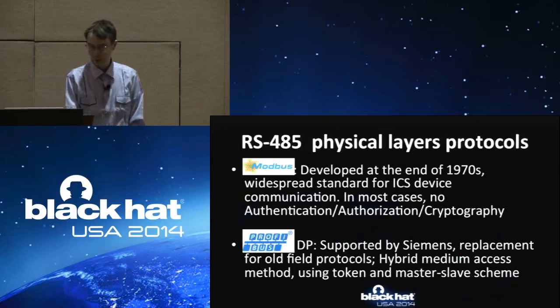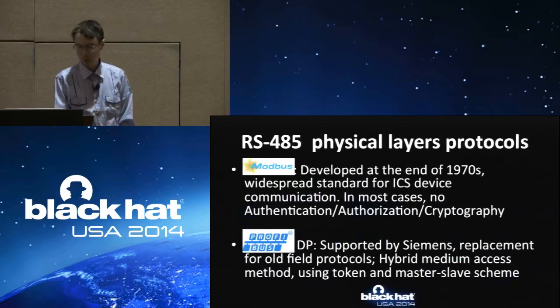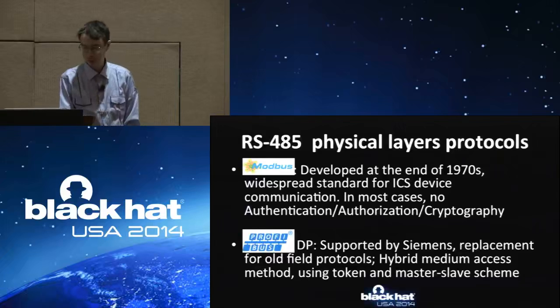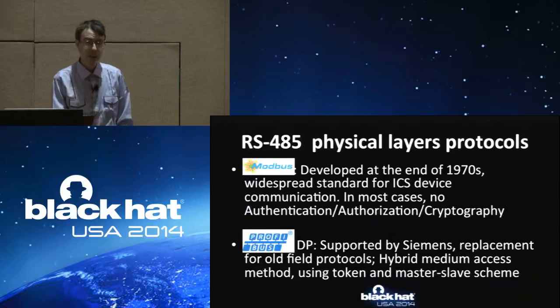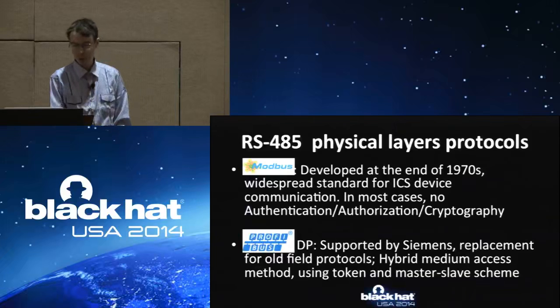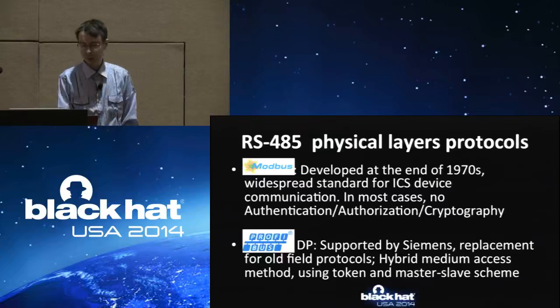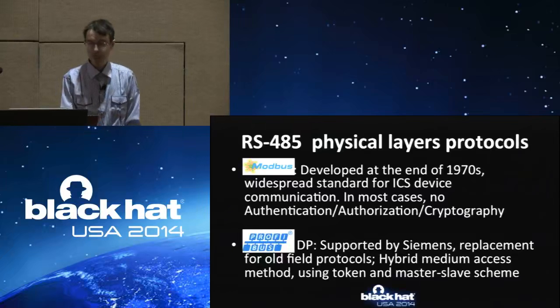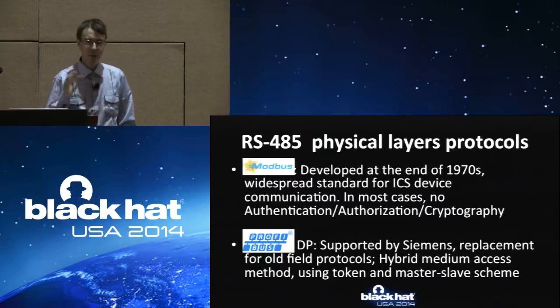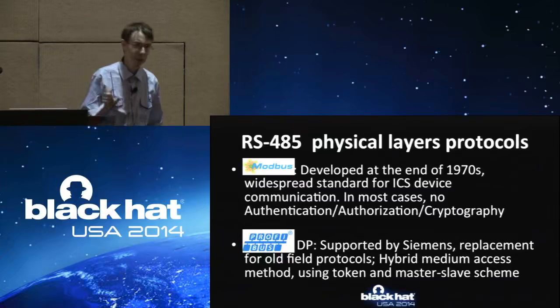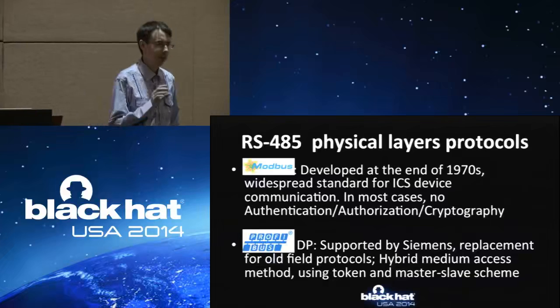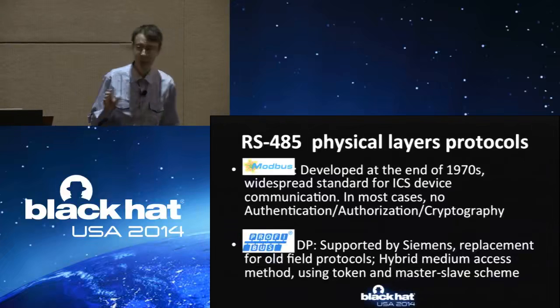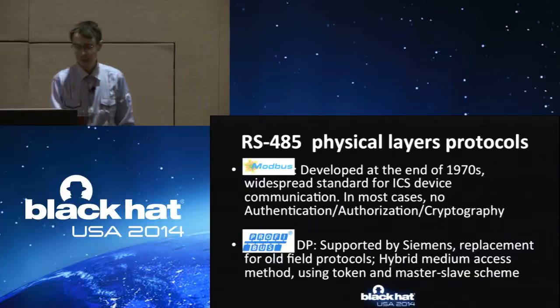In this talk, there will be no vulnerabilities of low-level protocols based on RS-485 shown. However, the board that I have developed, ICSCorsair, supports working with Modbus and Profibus, so I should mention these protocols here. Modbus is a very old protocol. It could work over RS-485. Mainly in Russia, we have many devices based on Modbus working over RS-485. And in most cases, it has no authentication, authorization, or cryptography.